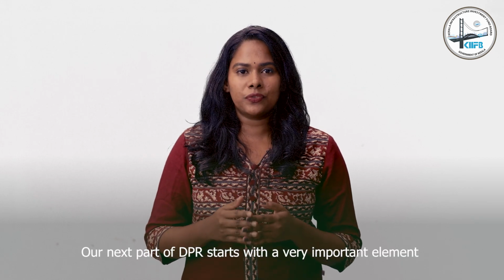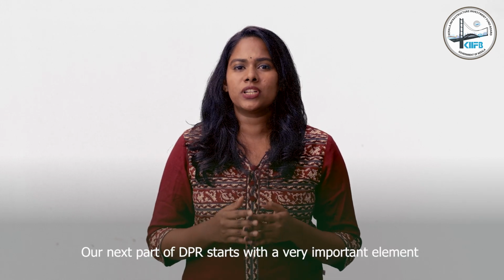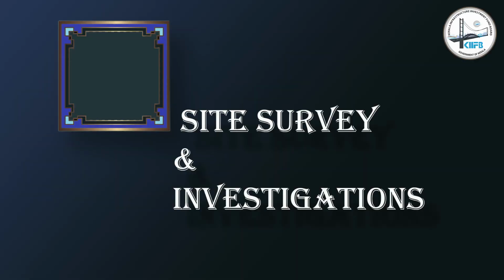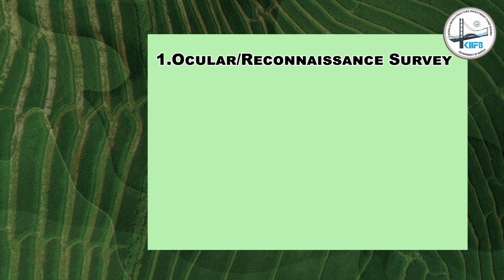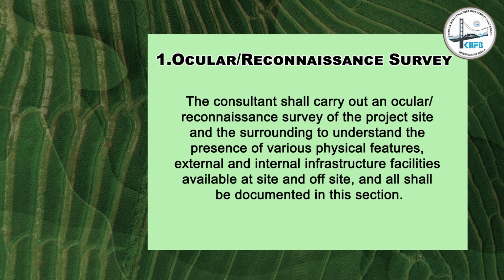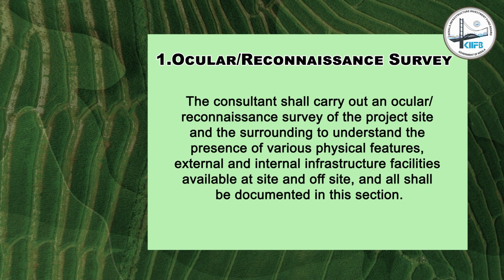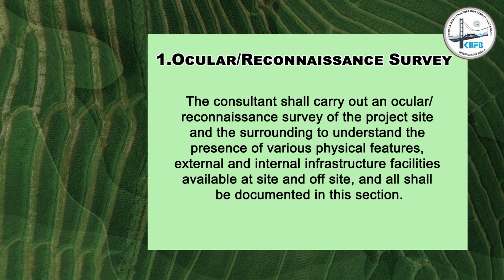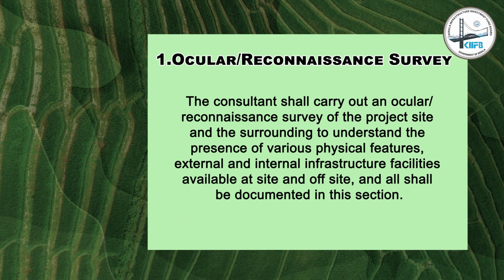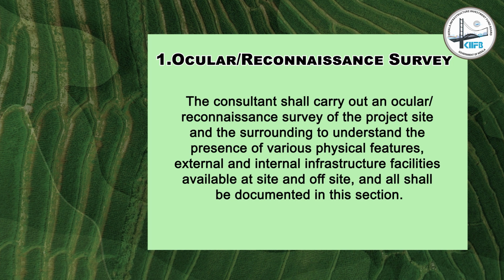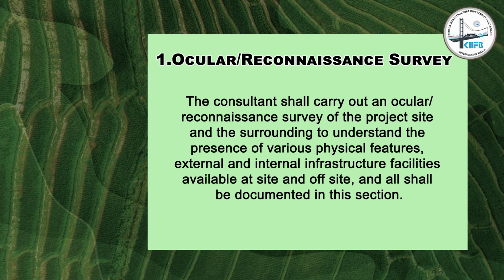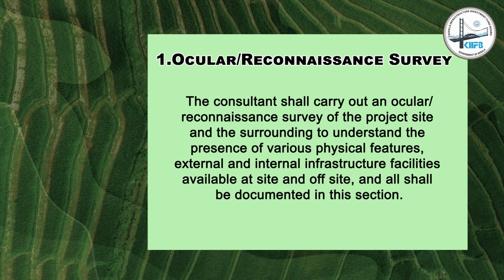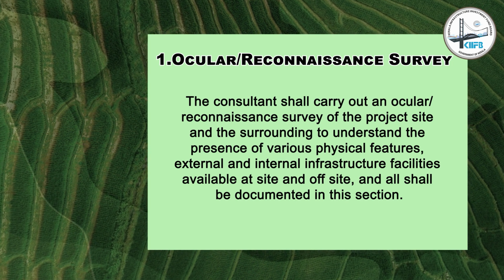Our next part of DPR starts with a very important element, site surveys and investigations. Ocular or reconnaissance survey. The consultant shall carry out an ocular or reconnaissance survey of the project site and the surrounding to understand the presence of various physical features, external and internal infrastructure facilities available at site and off-site, and all shall be documented in this section.